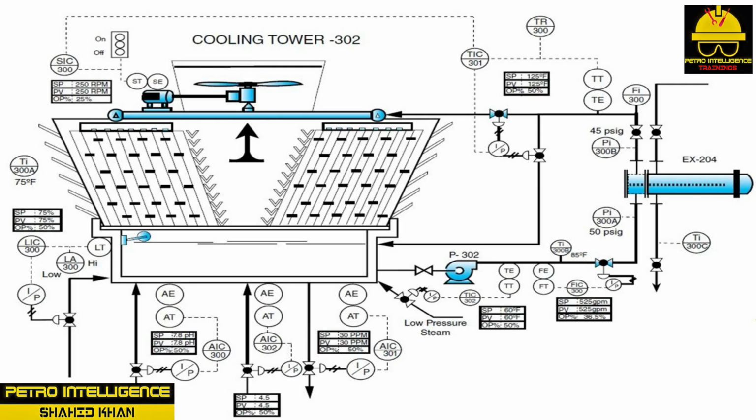Water distribution system consists of a 12-inch deep pan, 4 feet 3 inches by 20 feet, with holes equipped with stationary spiral nozzles that distribute the water across the fill. A pan with holes and nozzles is located on the east and west side of the cooling tower.